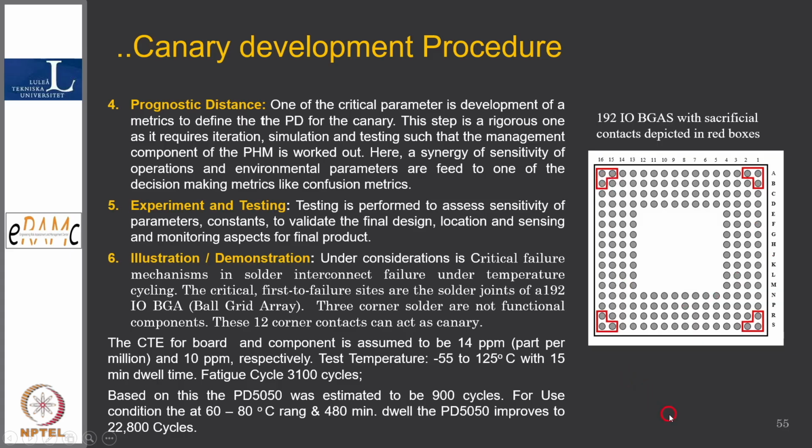Only then will it be called a canary, and for that a lot of experimental testing has to be done. So this is just an example I have given. The coefficient of thermal expansion for the board and the component is assumed to be 14 ppm (parts per million) and 10 ppm respectively. That is the coefficient of thermal expansion, how much it expands being a factor. Test temperatures were -55 to +125 degrees with a 15 minute dwelling period, and 40 cycles.